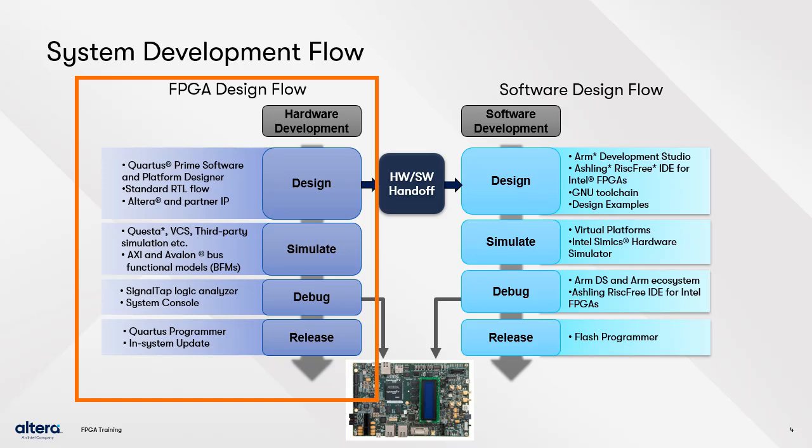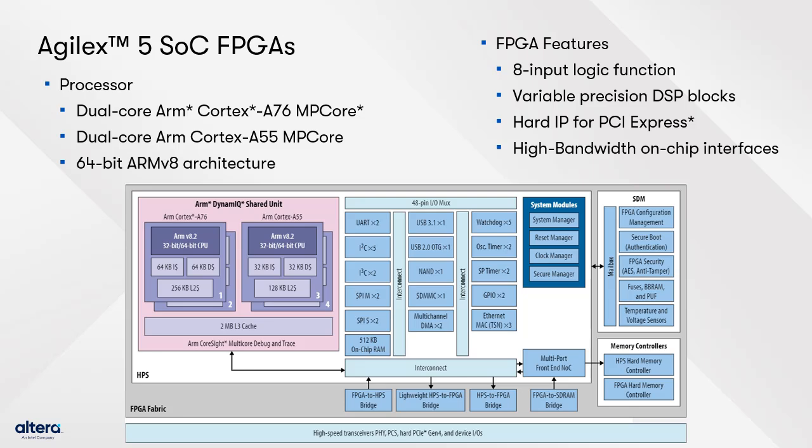Finally, once everything is ready, the FPGA hardware needs to be programmed and ready for release to make the software design flow go easy. Platform Designer system integration tools used to bring the hard processor system together with other components will generate handoff files.